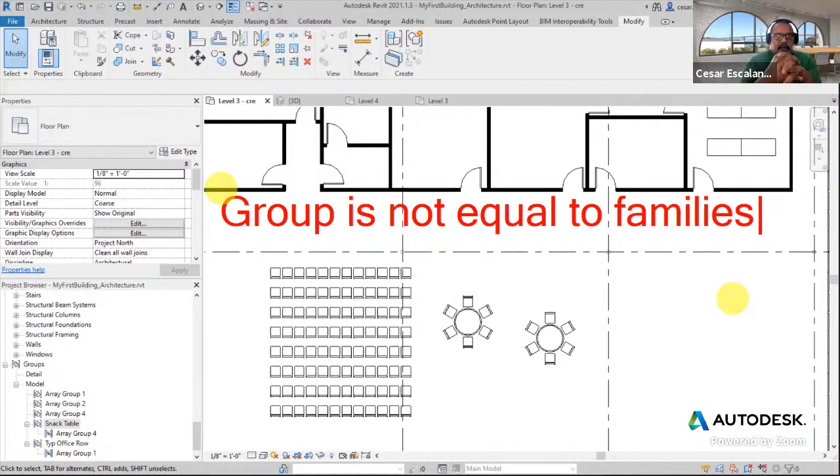For example, when you're doing an apartment type or a condo type, you're going to have in this group furniture like the bedding, the tables, the chairs. We're also going to have cabinets. You may have walls. You may have electrical equipment or electrical outlets. And when you have elements from different categories that need to be repeated in the project, that is the proper use of the group.